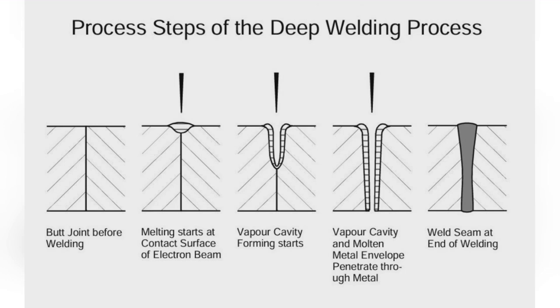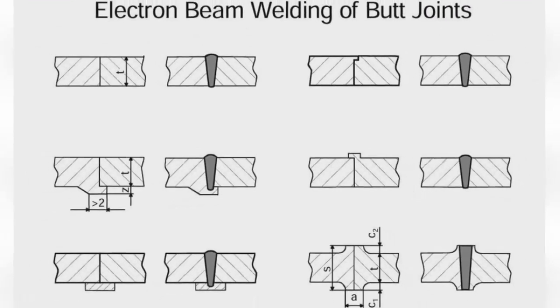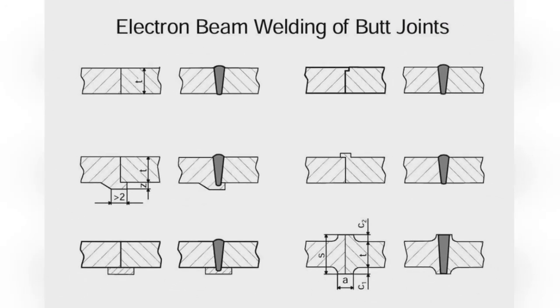The surfaces to be joined are mechanically worked or, as in the case of extrusions, have specially formed lips which help to position the parts to be welded and serve as weld pool supports. Weld pool supports in the form of grooved sections are usually not used, since the high-energy beam reaches right through to the bottom of the joint. This would lead to an undesired welding. The remaining weld pool supports tend to reduce the dynamic strength. For this purpose, joint forms and machining allowances are designed.